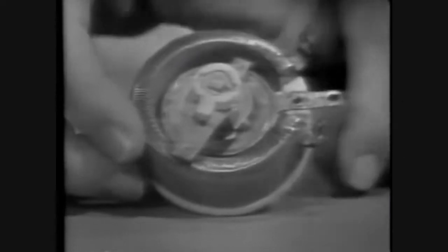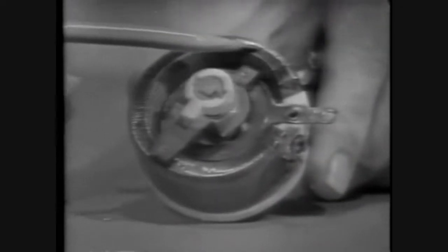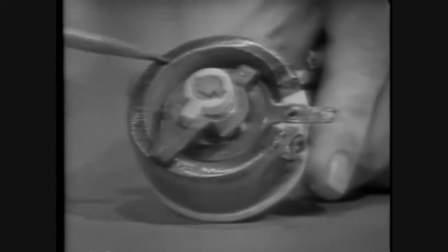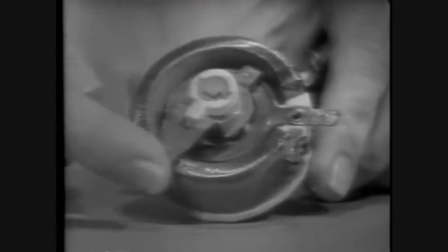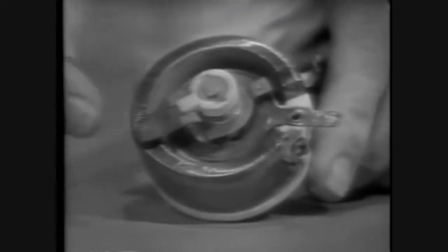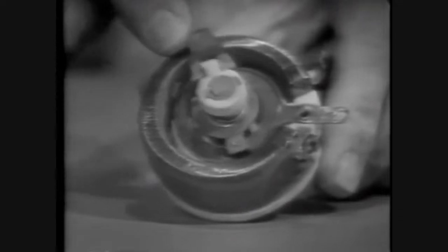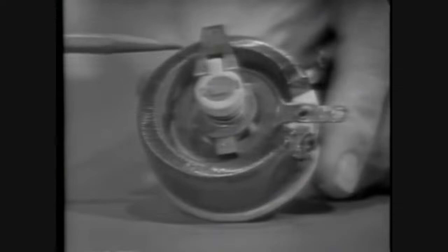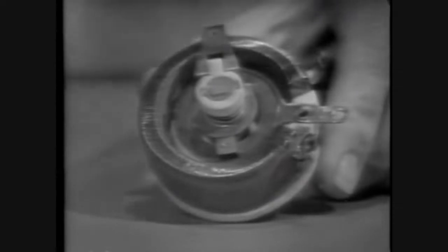Another common type of wire wound resistor is a variable wire wound resistor. The wire is here in this semicircle, and it's a fixed resistance from this tap to this tap. The variable part of the resistor is provided by this contact. For example, if I move the contact to here, I've increased the length of the material that I'm using from the contact to this terminal. Therefore, I've changed the resistance. When I move the contact, I change the length of the wire, change resistance. So a variable wire wound resistor. Again, you can select several different values of resistances from one resistor.